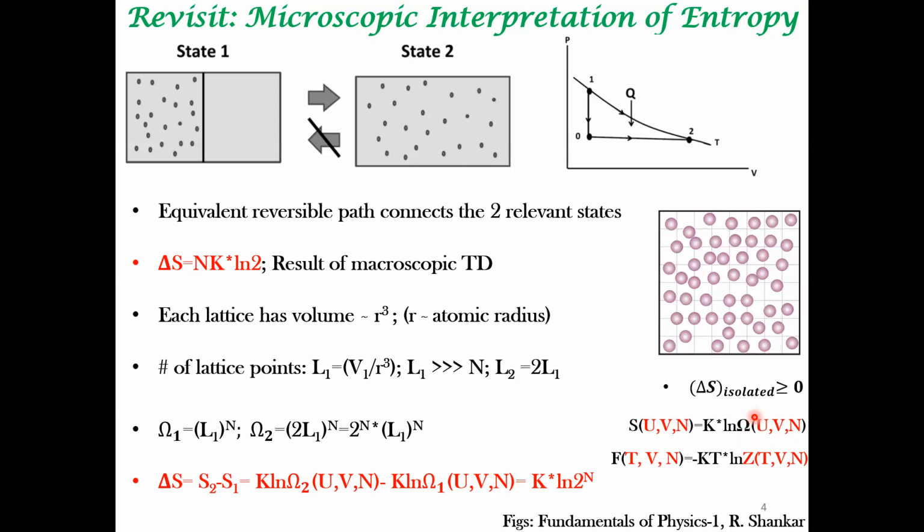All right, so there is a version of thermodynamics, postulatory thermodynamics or axiomatic thermodynamics. We say that corresponding to the control macroscopic variables, some particular thermodynamic function takes an extremal value. So supposing you control U, V, and N, entropy takes an extremal value.